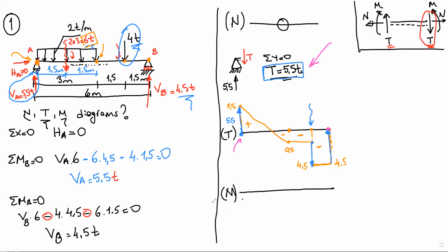So, to draw the moment diagram, we use the shear force diagram. How we use that? Remember, we calculate the integral of the shear force diagram. That means we calculate the area under the shear force diagram and add these areas to the moment diagram.